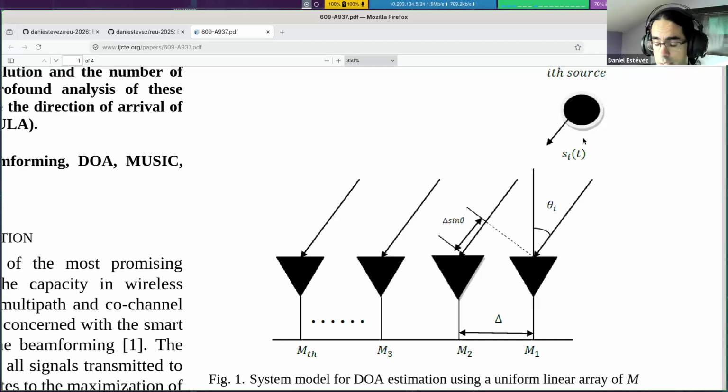In lower frequencies, it is more likely that we have omnidirectional antennas that can receive signals from any direction in the sky. That is great because it means that with our receiver, we can basically point anywhere in the sky and we can point to multiple places simultaneously. It's just a matter of compute, and we can make whole sky images. If any of you is working with LOFAR data or any of the other low frequency arrays, you might be familiar with what I'm talking about.